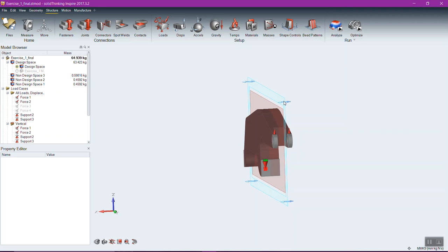But while additive is changing the world and allowing us to create things that we never have been able to create before, even they have manufacturing requirements. Whether you've got one of those little desktop devices that melts plastic and builds up, or whether you're laser sintering, which is a really cool process if you've never seen it, still, you're building up and up and up. Which means you can't have parts that are angled out too far, or you've got nothing to build the next layer on. So there are limits to that too. Even with additive, which is creating things that are just absolutely amazing, there are manufacturing requirements there too.